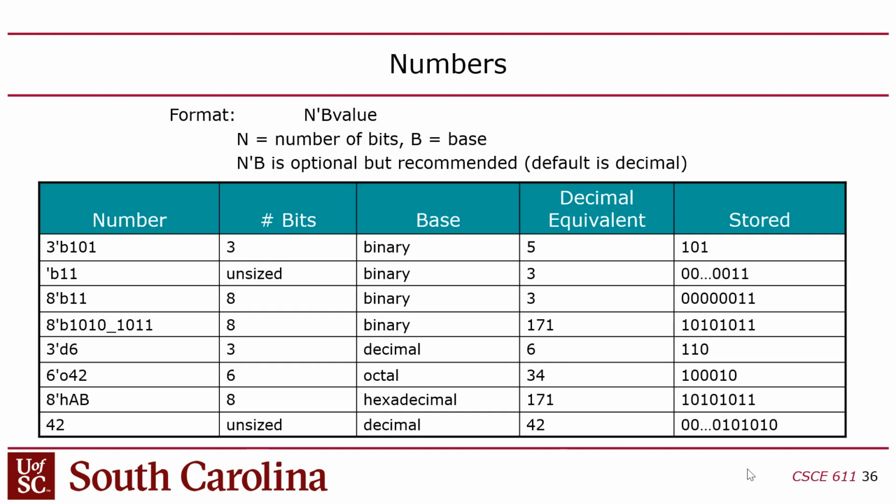Okay, and then the other thing too is another consequence of the logic type not being standard data types. In Java and C, you've got int and short and char, which have these predefined widths, number of bits. With logic, there's really no default bit width.